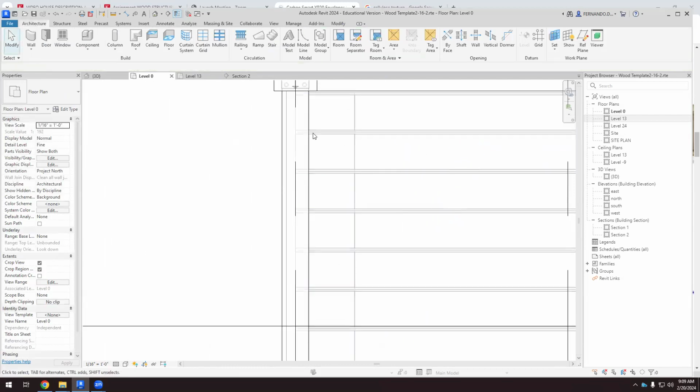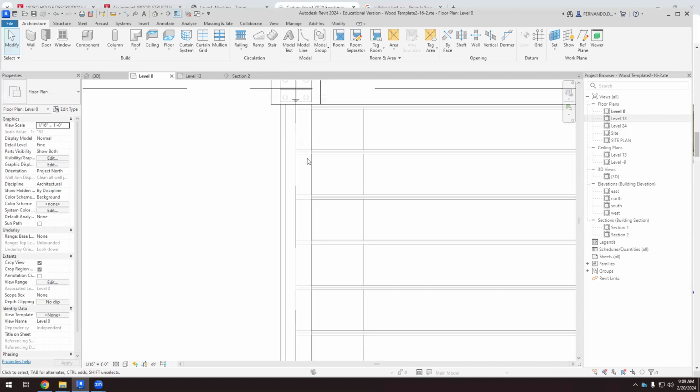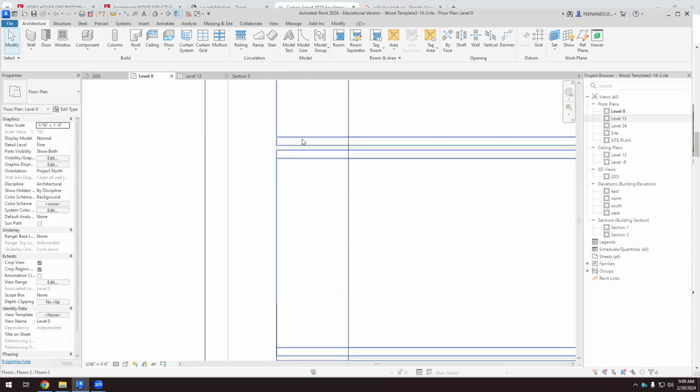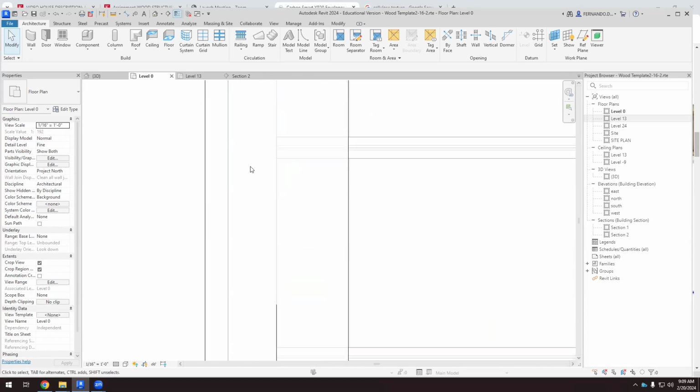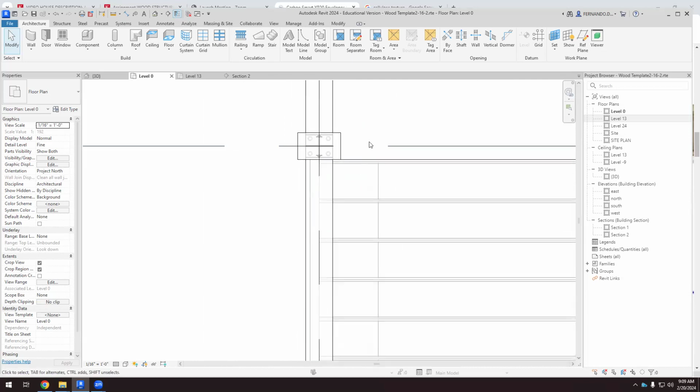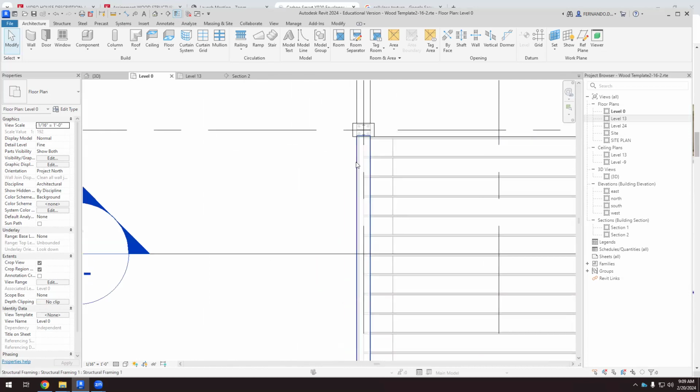So I'm going to create studs, a 2-inch stud, and the width is going to be 10 inches. So I'm going to create studs 2 by 10. I can create a component model in place, or just to do something different, I'm going to create a structural element.